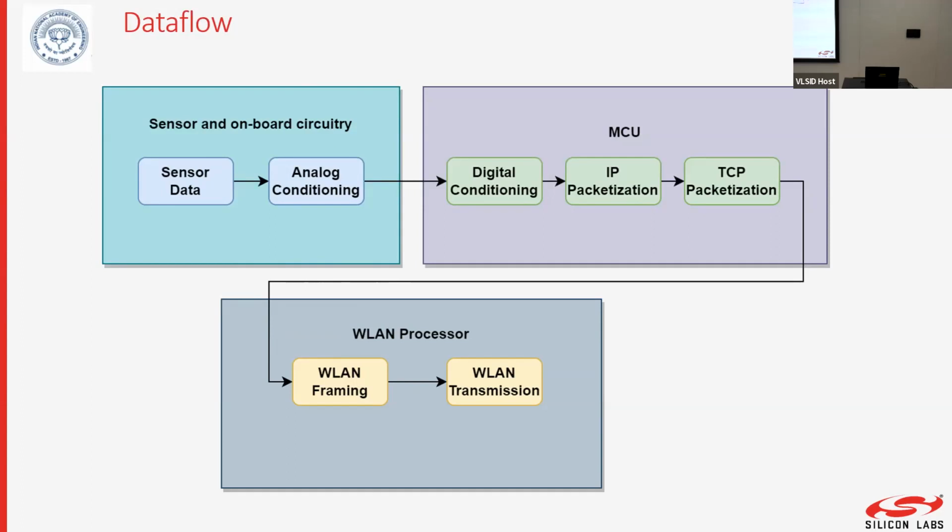If you make a mistake, you have to redesign the FPGA and burn the bit file again, which is why all FPGAs today have microcontrollers built in. Xilinx included. They know that some part of it, people will make iterations. So FPGAs, by the way, are not really energy efficient. But the difference between hardware and doing it in firmware is that firmware has more flexibility. Hardware can do things at a higher speed if you want to do things at a higher speed.